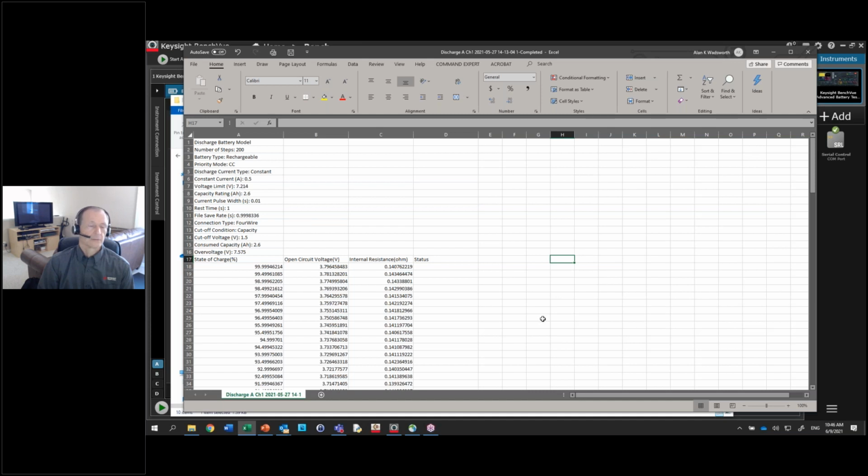Okay, good. The next question is, can you use a virtual battery to test your test routines, to try them before connecting to a real battery? So this goes back to almost the same exact question, which is basically, with the model you don't have to discharge an actual battery in order to use our emulator. If you have the content of the model containing the open circuit voltage, state of charge, and the series resistance, we could just emulate it. So for example, if you just have like 10 points from 100% all the way down to 0, and you put in those parameters of state of charge, and then you also put the parameters for open circuit voltage and internal resistance, we simply could just simulate that.